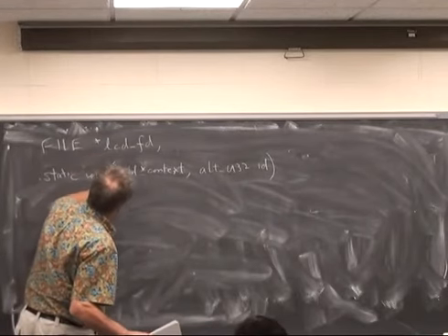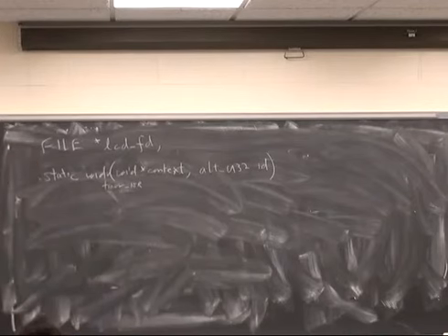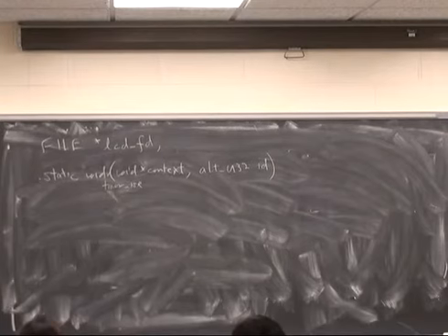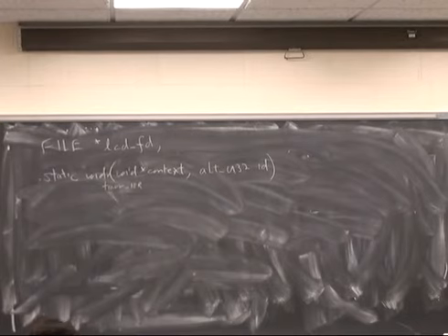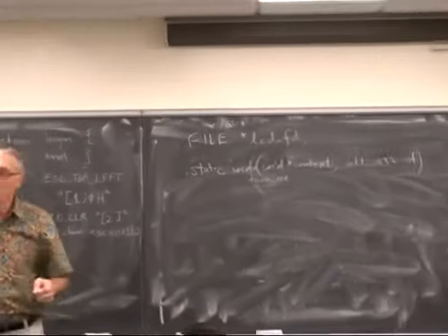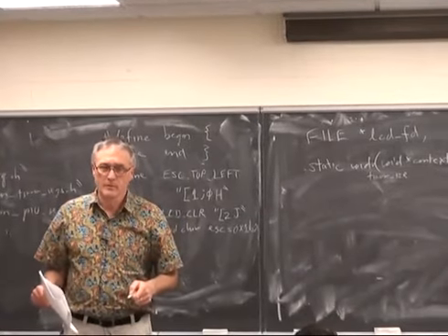We'll just call this timer ISR. It is written as if it's a function. And the way it becomes an interrupt service routine is in main, you have to identify to the interrupt handler the name of the function which is to become the interrupt.